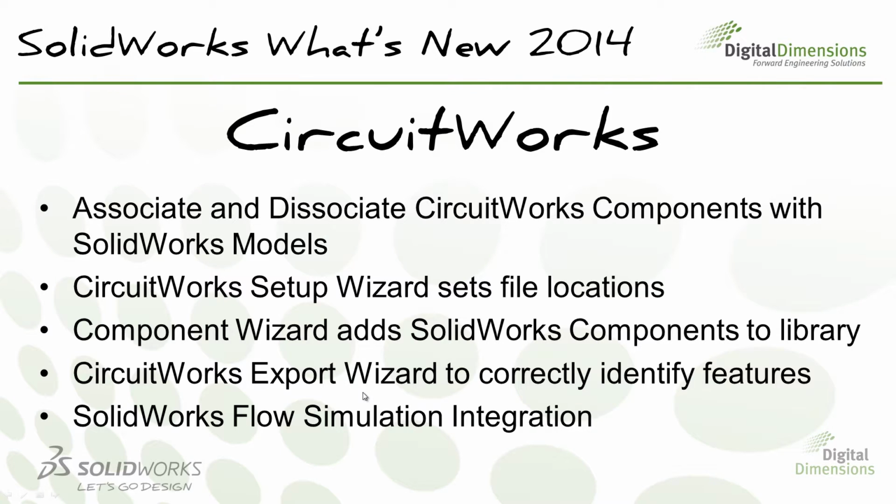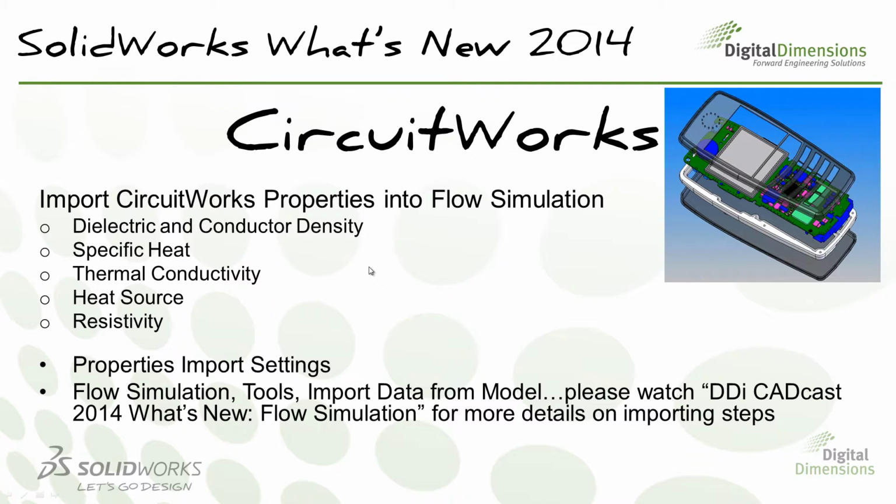The next thing I want to talk about is SOLIDWORKS Flow Simulation integration, where now there are some settings inside of CircuitWorks to allow custom properties, in this case thermal properties and material properties, to be transferred directly from some of this ECAD data into the flow simulation studies. Some of those studies need properties like the specific heat and thermal conductivity.